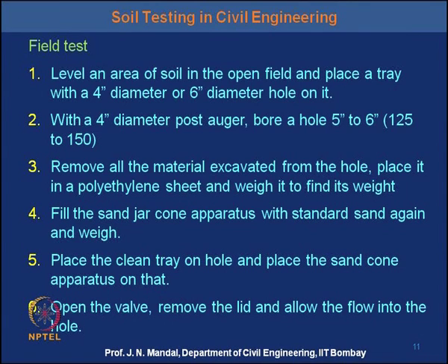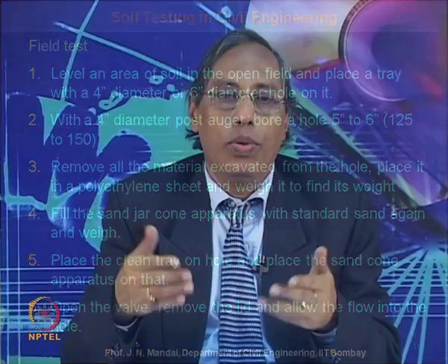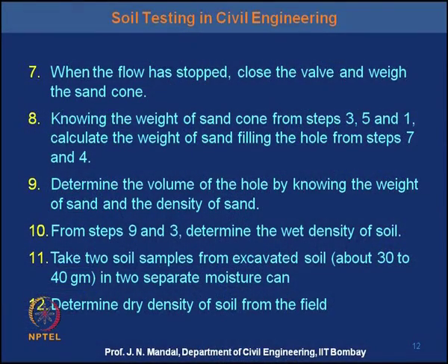Place the clean tray on the hole, place the sand cone apparatus on that. Open the valve, remove the lid and allow the sand to flow into the hole. When the flow has stopped, close the valve and weigh the sand cone.